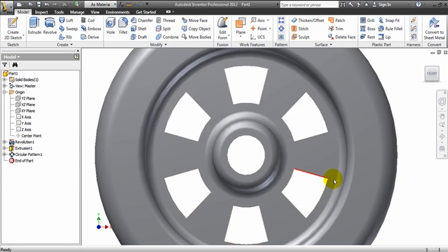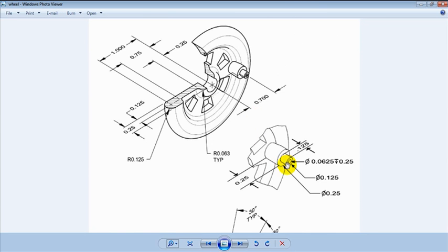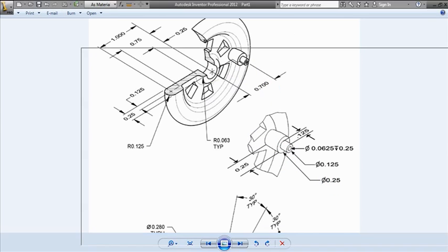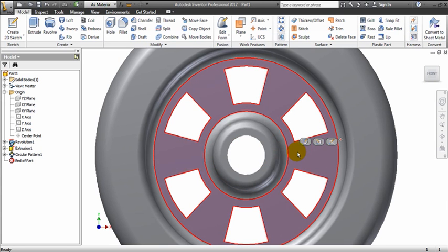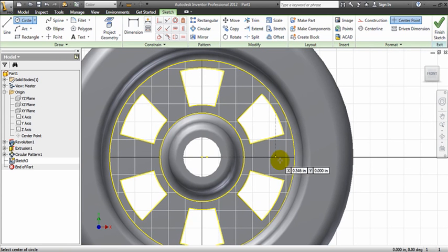And I'm going to make the little peg thing now. So the little peg is right here. It is 0.7 inches away from the center. Oh, and the very outer ring is 0.25 diameter. So I'm going to make that one first. I'm going to go to Inventor, make a sketch right here because it's going to go on this face. I'm going to grab my circle tool, make sure it's in line with my center. 0.25 is going to be the diameter.